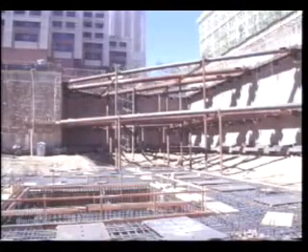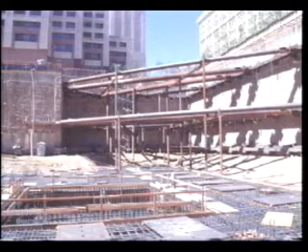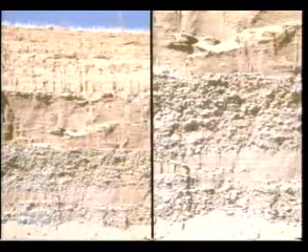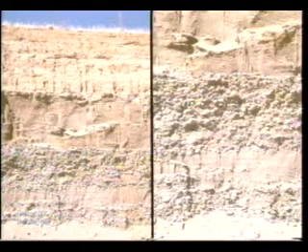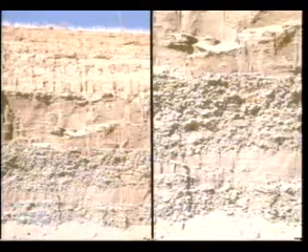The type of investigation is also greatly affected by the soil type and variability. A structure founded on a homogeneous layer of clay may require high-quality samples to accurately predict the amount and rate of settlement. But if the same structure is on soil consisting of pockets and lenses of clay, silt, and sand, information of greater value may be obtained by taking a greater number of less expensive disturbed samples to determine the location and size of these pockets and lenses.